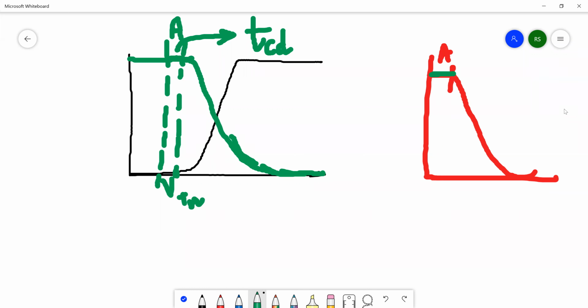You know what inertia is in the physical world, right? There is some amount of resistance for the action to happen. In some cases, you can think of this also as the same thing. There will be some amount of time before the output starts to respond to the input. That small amount of time, tCD, is very small. It's not big like propagation delay. You will not get 50 picoseconds. It's much smaller, 2-3 picoseconds, but it is still not zero. There is some amount of time before it starts to respond, and that is called the contamination delay. You might not have heard this before, but it's a very simple concept, very similar to inertia.